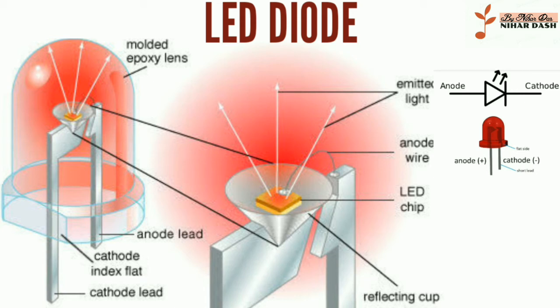When the forward biased current, IF, is applied through the p-n junction of the diode, minority carrier electrons are injected into the p region, and corresponding minority carrier holes are injected into the n region. Photon emission occurs due to electron-hole recombination in the p region. Electron energy transitions across the energy gap, called radiative recombinations, produce photons, i.e., light, while shunt energy transitions, called non-radiative recombinations, produce phonons, i.e., heat.